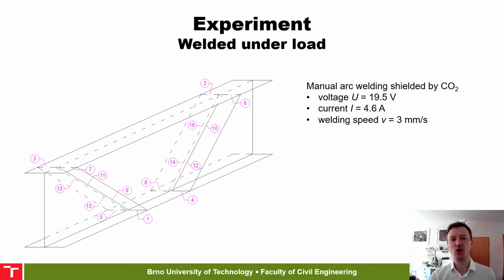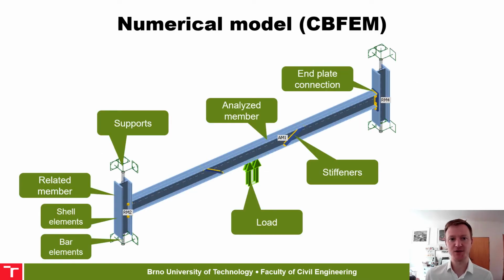For welding under load, I prescribed a specific welding sequence so that the beam cross-section is not weakened all at once, and has a time to cool down. However, I do not want to talk about it in detail now. I want to focus on the general numerical model created by Ideastatica in a joint research project.